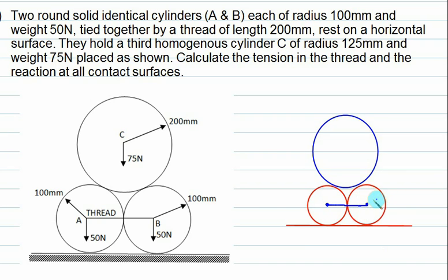And therefore every time this cylinder will try to go this side and this cylinder will try to go this side. So the length of this member always increases. If the length of the member tries to increase, then a hair gap is produced here. A small hair gap will be produced. Therefore, these two cylinders will lose contact. But this cylinder and this cylinder will be in contact, and this cylinder and this cylinder will be in contact. So the contact between these two cylinders is always there. But because of this cylinder, they will lose the contact. So it will go slightly rightward.